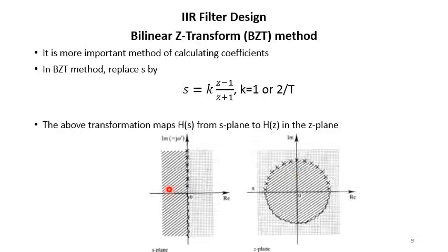Based on the Laplace transform, because H(s) is the system function in the Laplace transform, by previous knowledge you understand that poles lying in the left half of the s-plane correspond to a stable system, whereas those lying to the right mean an unstable system.